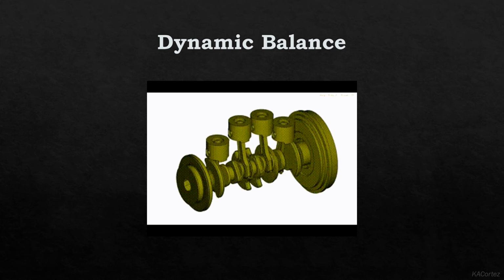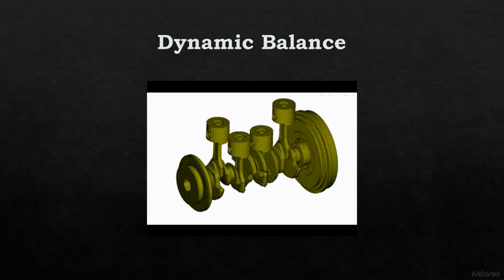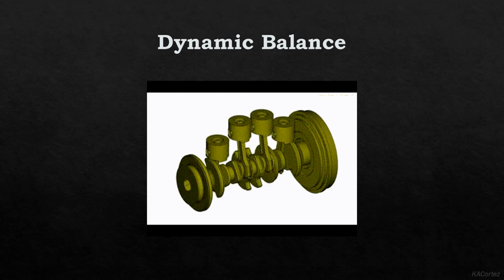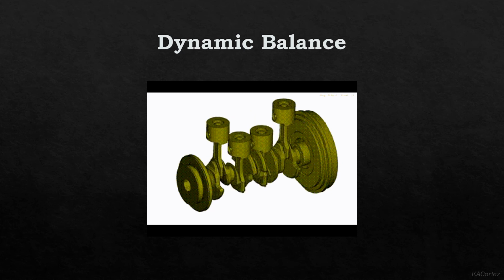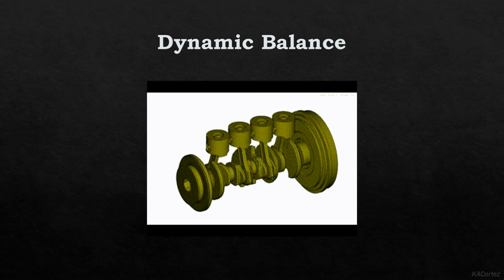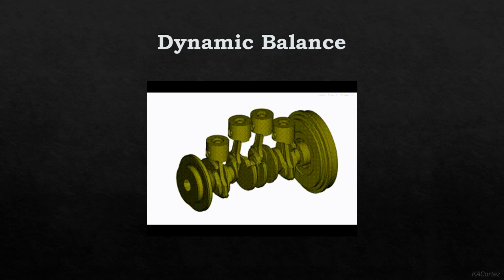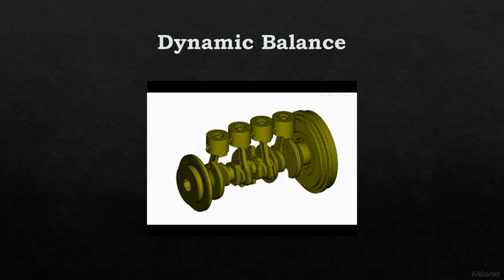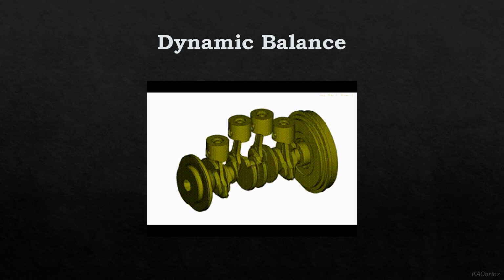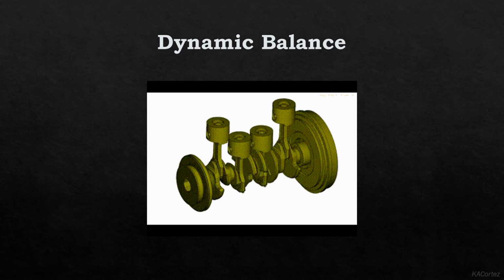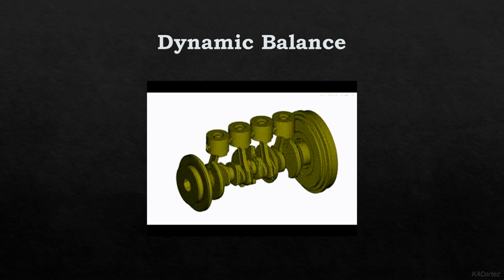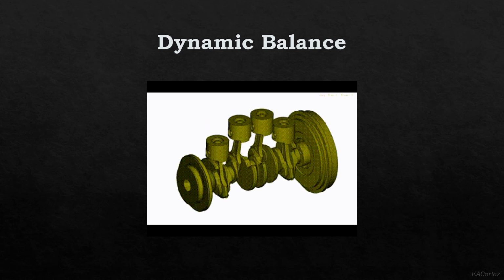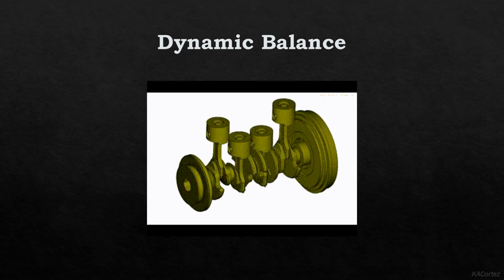Each time a cylinder fires, a pulse is transmitted into the crankshaft that causes it to flex. When the engine is running, the crankshaft receives hundreds of these pulses each minute and flexes, or vibrates, constantly. To help minimize this vibration, the dynamic dampers oscillate, or swing, each time the crankshaft receives a pulse from the firing cylinder. These oscillations are opposite the crankshaft vibrations and therefore absorb some of the force produced by the power impulse.